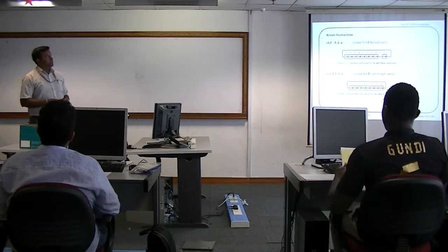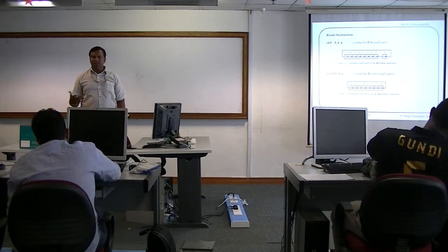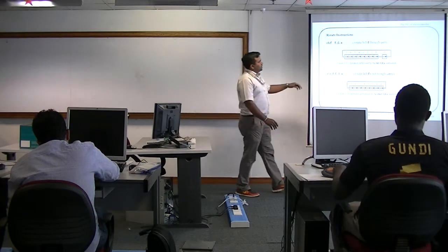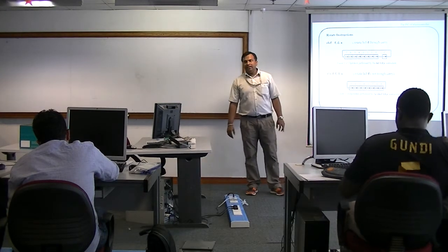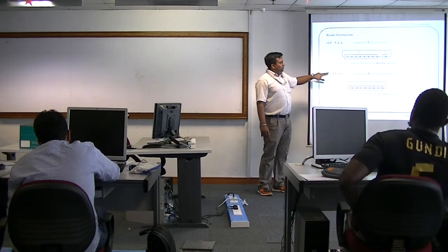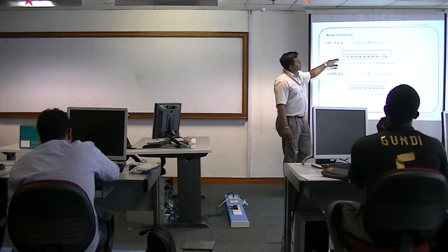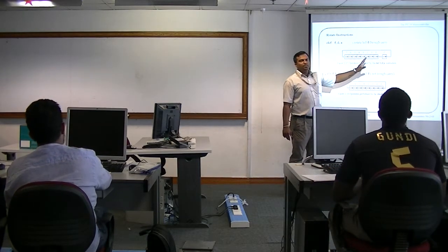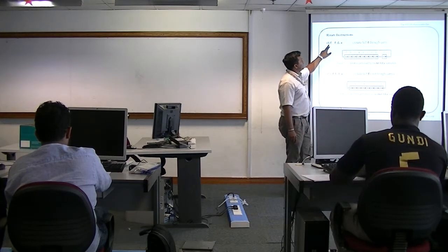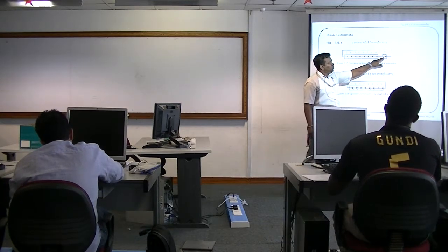So basically there are two rotation instructions, one is rotate left and one is rotate right. And this is rotate left. There are two types of instructions for rotate left. One is rotate left through carry, another one is rotate left not through carry. So rotate left means you rotate every single bit by one position to the left. Now the first instruction, rotate left through carry. This one actually goes through the carry.